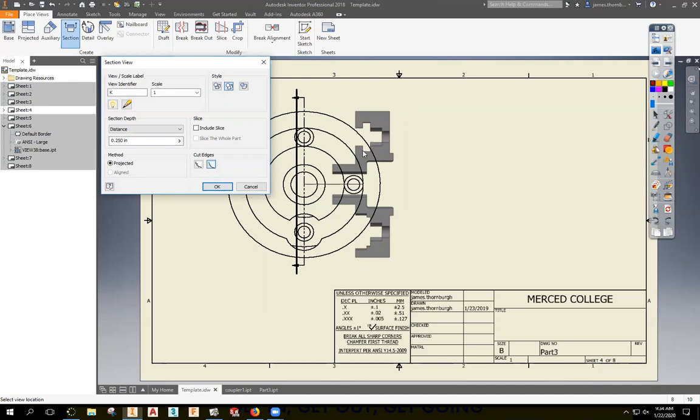In most cases, you want from the cutting plane to the rest of everything. In some cases, you've got a lot of stuff going on, and it's going to get confusing, so you want to do just slices of it, which you'll see in a couple slides. In that case, we would use that distance option and just do from that cutting plane to the next thing.